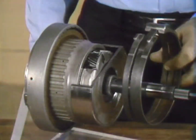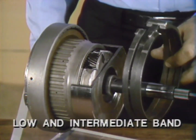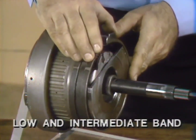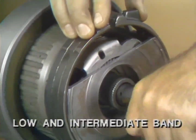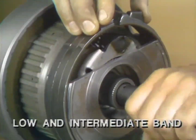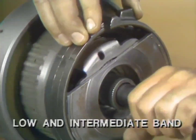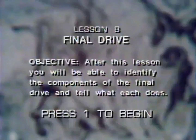The last holding member for the gear train is the low and intermediate band. The band also is mounted stationary in the case, around the drum, which is part of the forward sun gear assembly. And so when the band is applied, in first and second gear, the forward sun gear is held stationary. With the sun gear held stationary, the long pinions are forced to walk around the sun gear.